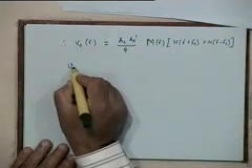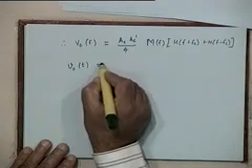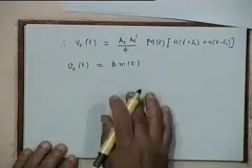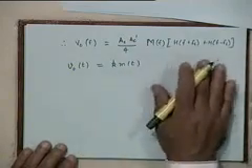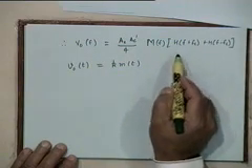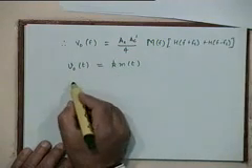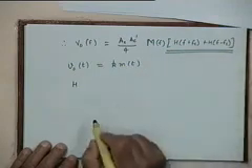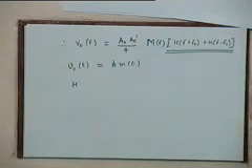What do we want? We want our V naught of t to be proportional to m of t, k times m of t, right? So what does that tell you? What can we say about the filter H of F? What condition should it satisfy so that this happens? This function of frequency which is coming from these two terms, which are coming from the filter transfer function, should be equal to a constant value, right? They should not be a function of frequency, right? That's what it means.